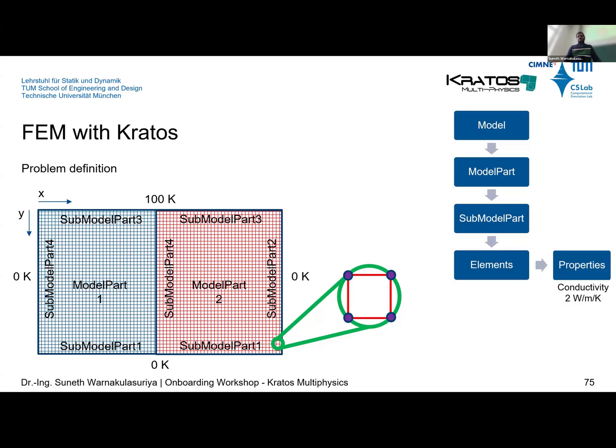Then you have another concept called conditions, which are only present at the boundaries. They always share nodes with some elements. Those are to represent the boundary conditions. They can be Neumann boundary conditions or Robin conditions, basically. So it has a contribution to the system matrix.